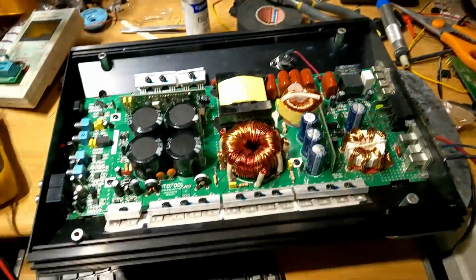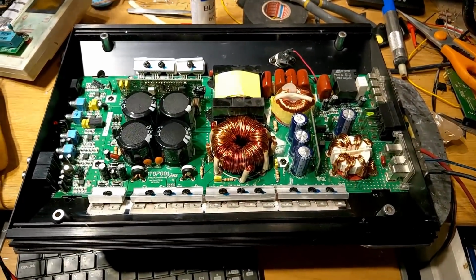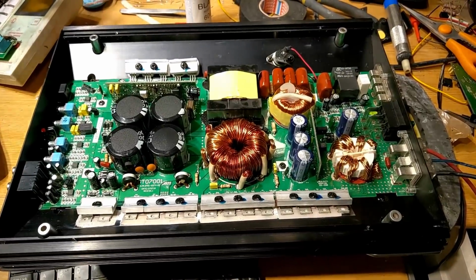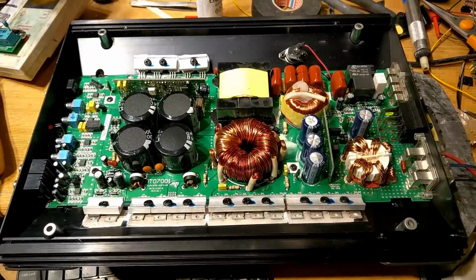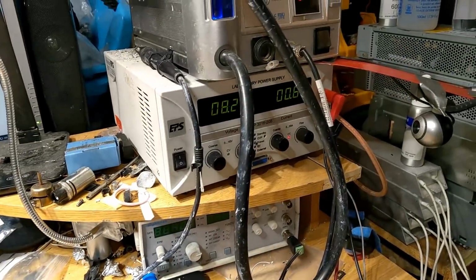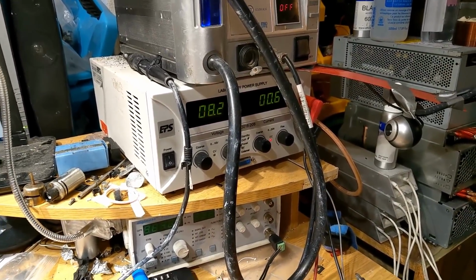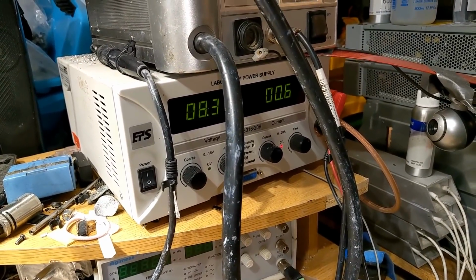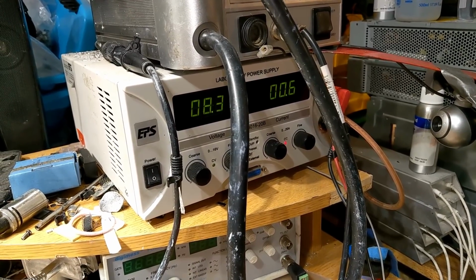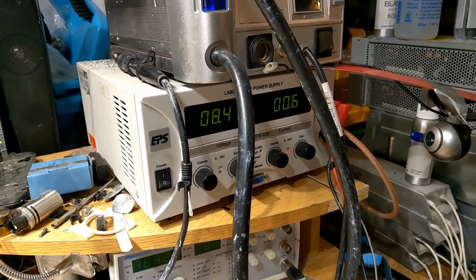So I guess it's similar to refurbishing a battery. If a battery has become critically empty, you can get it back to life by slowly charging it over a long period of time. So this is a similar thing, but for capacitors. I've never really seen this before, only on these amplifiers. And once this voltage does reach up to 16 volts, I will then be able to turn it off and turn it back on again, and there'll be no current draw.